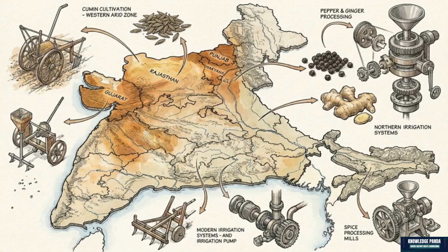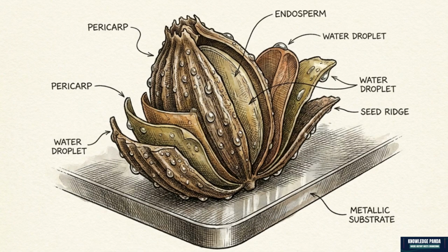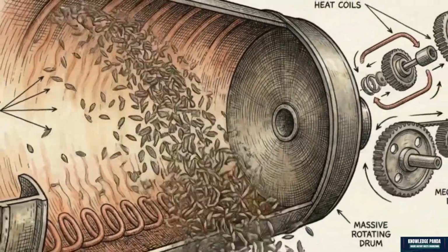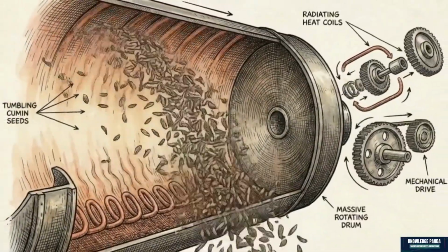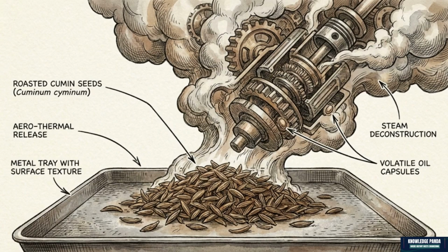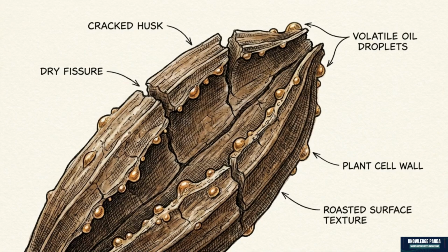The closed-loop liquid system operates in stark contrast to solid-state manufacturing, which relies on highly variable raw agricultural inputs sourced from arid climates. Raw biological crops carry unpredictable flavor profiles and excess internal moisture. They require immediate thermal activation upon entering the facility. During the desiccation process, massive industrial roasters heat raw cumin and heavy spices to exactly 130 degrees Celsius. Hitting this specific thermal threshold achieves a dual purpose. It rapidly vaporizes excess water weight, while simultaneously forcing the plant cells to release their dormant, volatile flavor oils.